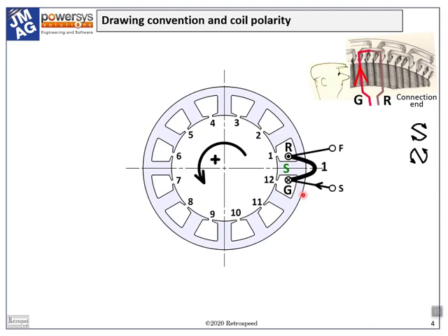Before we leave this diagram, let's just note the positive direction, which is anti-clockwise. This is the mathematically positive direction, which makes sense here because we are taking a somewhat analytical approach. It's not necessarily the convention used in factories and winding shops, but here we will measure angles in the positive anti-clockwise direction, and that is also the direction of positive rotation.